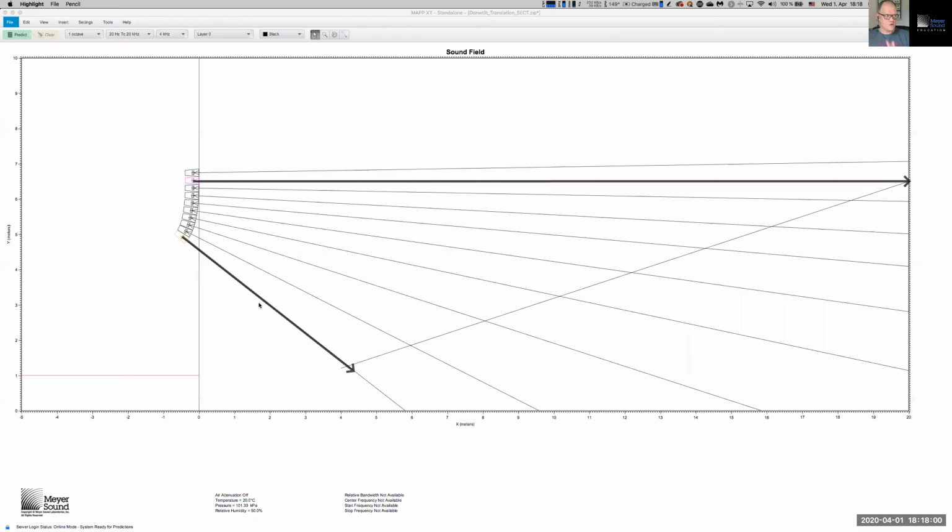But that bottom loudspeaker currently runs on a diagonal. And I cannot see that propagation plane, which currently runs diagonal, in plan view undistorted, because the loudspeaker that I see in plan view undistorted, that is to say, to scale, is loudspeaker number 2 from the top, the one whose propagation plane runs level, parallel to the drawing plane. So now we need to come up with a solution to still understand what is going on and to see whether we have enough coverage in that first row, which I cannot determine in plan view.